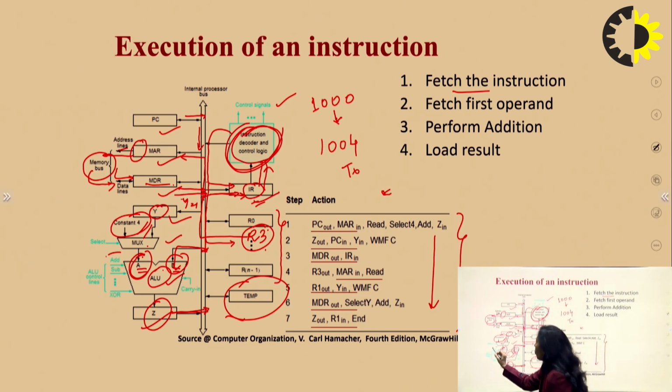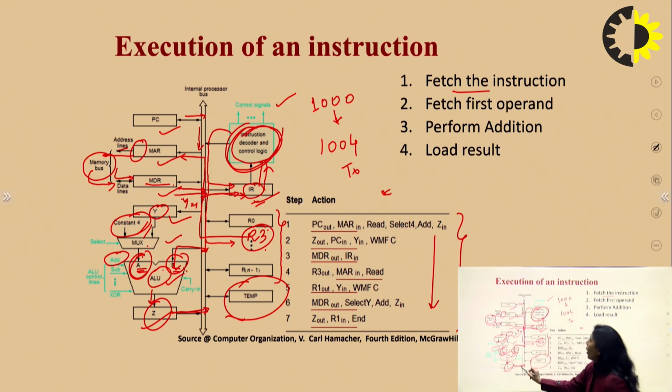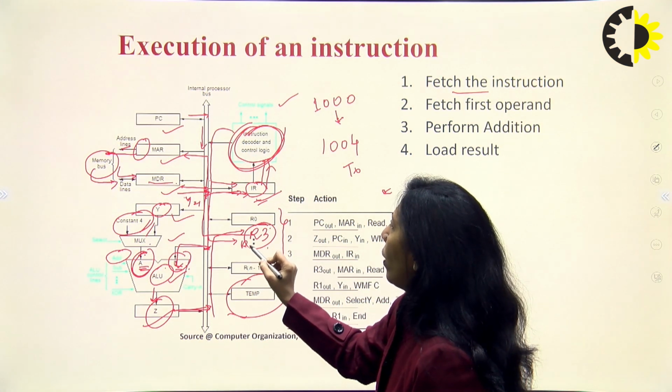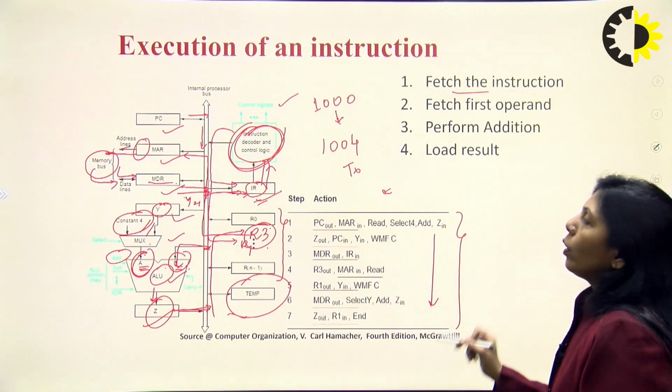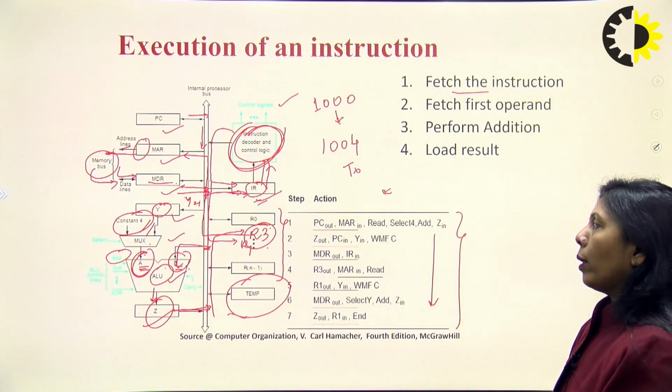If it was pointing to the add operation, that means the ALU needs to add these two values coming in via the A and B inputs. Now this added value will be given to the register Z. This register will give the value to the bus again, and in this way the value will be stored to R1.